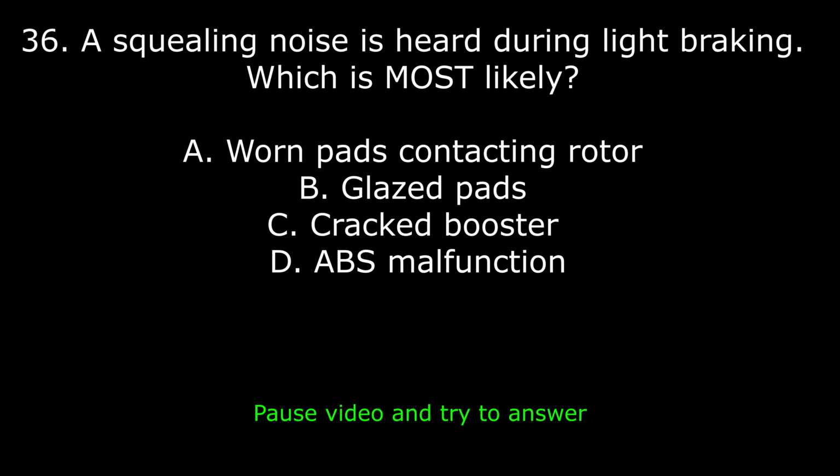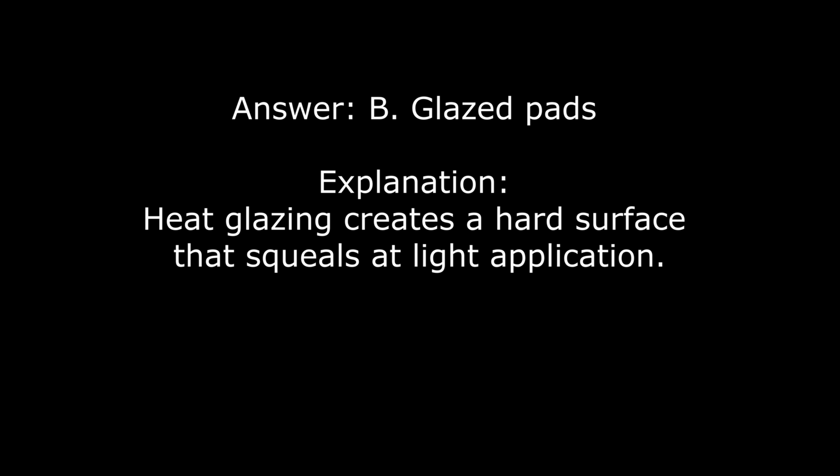36. A squealing noise is heard during light braking, which is most likely? A. Worn pads contacting rotor. B. Glazed pads. C. Cracked booster. D. ABS malfunction. Answer is B. Glazed pads. Explanation: heat glazing creates a hard surface that squeals at light application.